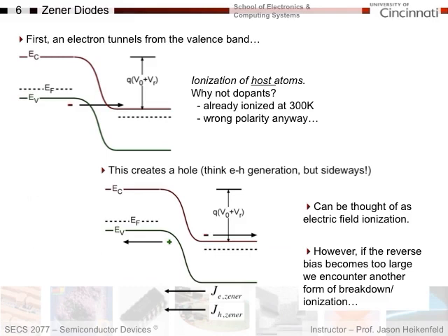And so let's see how this could happen. So I put a large reverse bias on this, okay, which means I put positive here and negative here. So if I put reverse bias on this, it's the same as putting positive voltage on this side and negative voltage on this side, okay? So in terms of current direction, obviously based on the electric field here, I want electrons to go this way and holes to go this way based on the voltage that's applied, right?